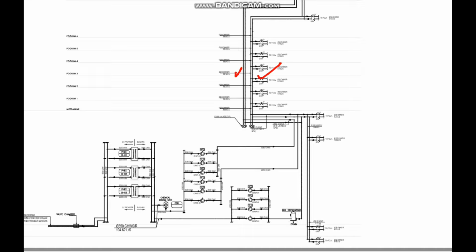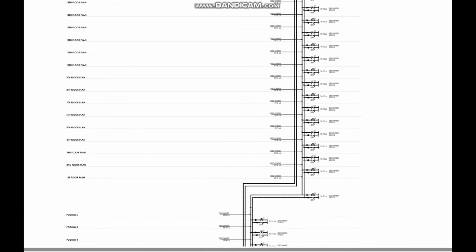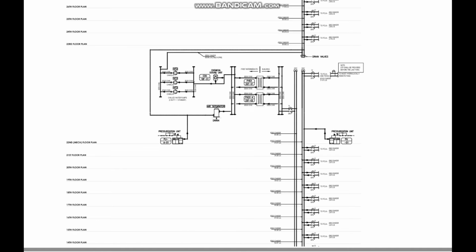So in this loop, for example, you can see one supply temperature which is going to another mechanical floor heat exchanger. Let's say if I go upside, you can see there is an intermediate flow. There is another heat exchanger in the intermediate flow. So as I told, if you have a super high-rise building, or any kind of 400 or 300 meter height, whatever it is, you have to have multiple heat exchangers.